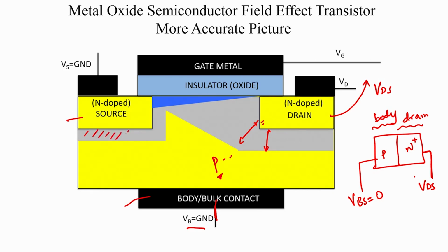For all practical purposes, it will have the same depletion width as one would expect in equilibrium, okay, with the exception that you have an active gate field right now. So, you will find that the depletion layer in this region is going to be much smaller as compared to the depletion layer thickness near the drain side.